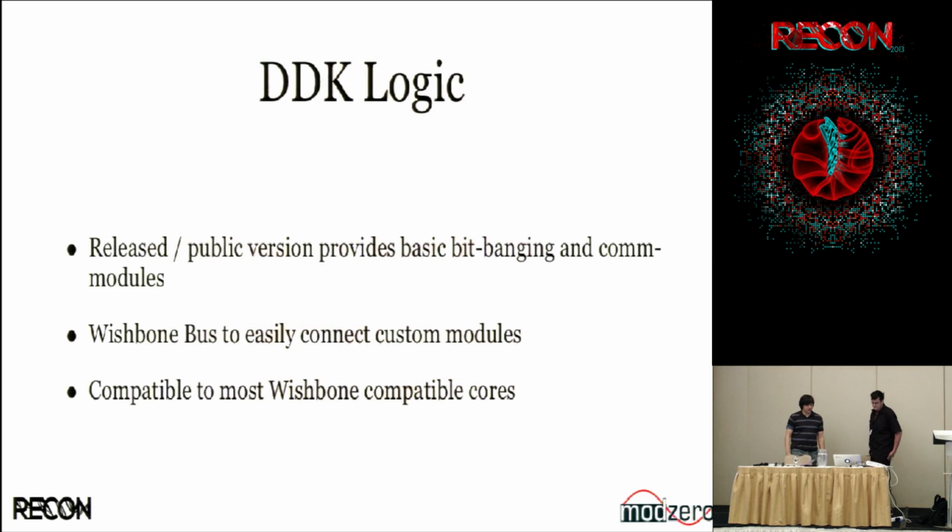Okay, so with the logic, what we synthesized up until now is just basic bit banging, just so that people can get a feel for the architecture. So if you look at the source code, you'll see that there are channel interfaces, and you can just swap these out and implement a custom channel module, and all of a sudden it won't be doing bit banging anymore, it'll be doing whatever you implemented.